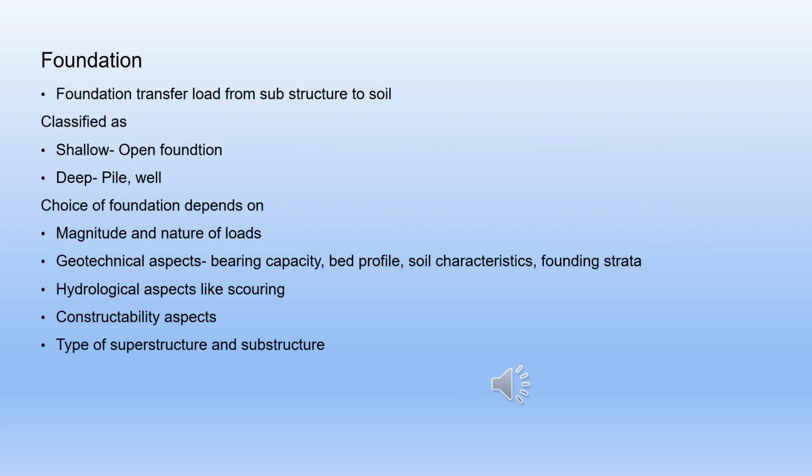The foundation transfers the load from the substructure to the founding strata, which is either the bedrock or soil. Foundations may be broadly classified into shallow and deep depending on the depth of the foundation. Bridge foundations are usually of three types: open foundation, which is a type of shallow foundation, pile foundation, which is a deep foundation, and well foundation, which is also a deep foundation.